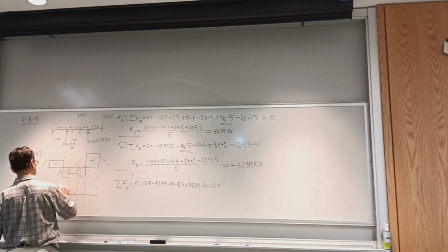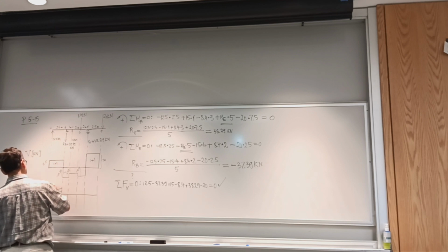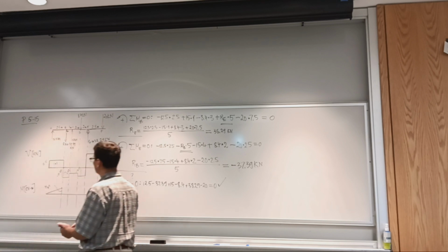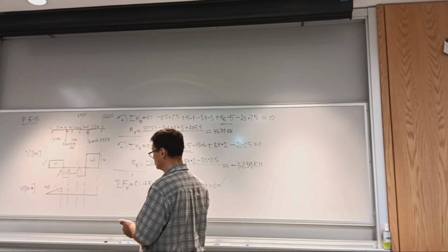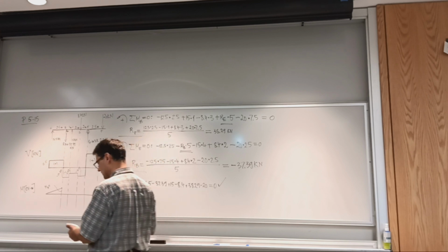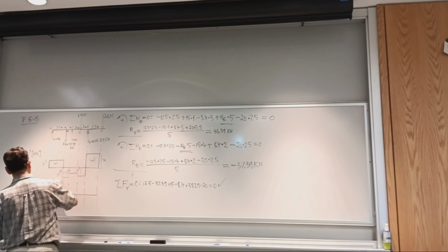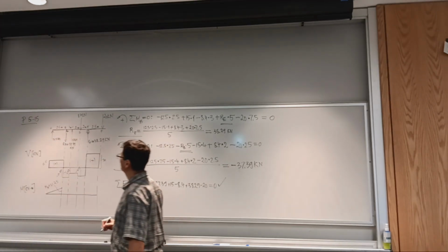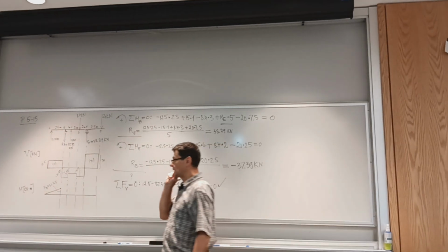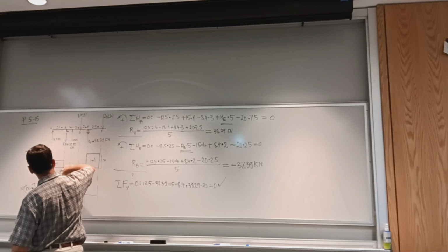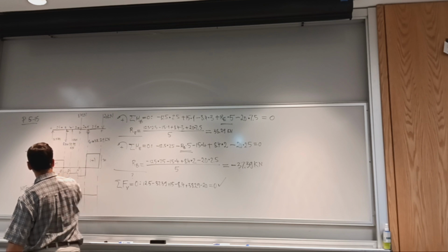And we can evaluate the moment at B. The moment at B is going to be this area. So what is that area equal to? 12.5 times 2.5. And this is 31.25 positive. Okay, so I'm at point D with the moment diagram. The slope changes to a negative one and more severe, double this.